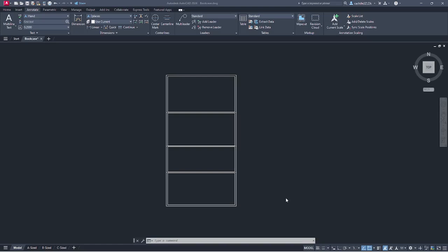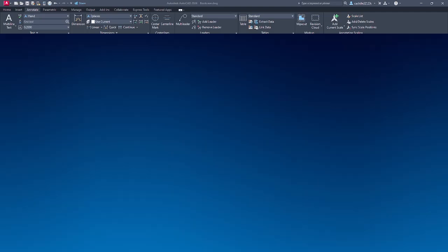In this practice, you will add geometric and dimensional constraints to objects in the block editor. You will modify dimension parameters and create user parameters, assigning values and formulas. You will test the block and flex the parameters to test how it works. Finally, you will create a block table with the sizes so that the blocks can only be modified by size.